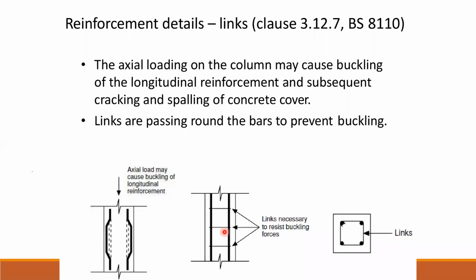The third, which we are not supposed to study here, is to improve the ductility, through what we call the volumetric mechanical ratio of the steel, which Eurocode 8 has recently included. That supports dissipating energy within a structure. You won't learn that at undergraduate level, but for sure in postgraduate study you will be learning all these things.